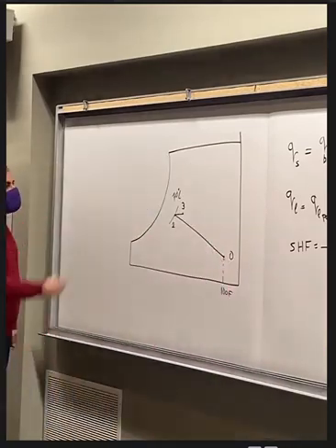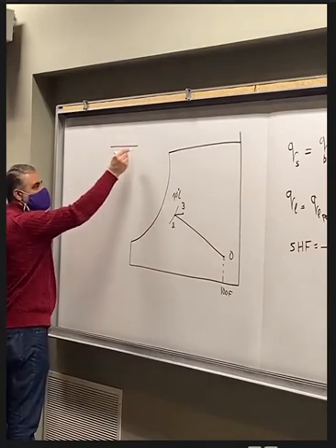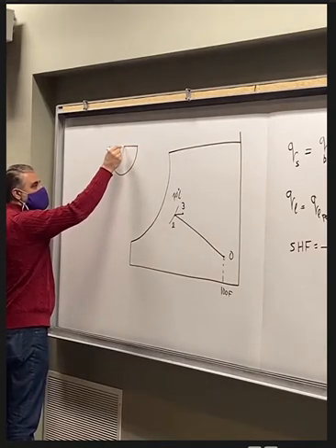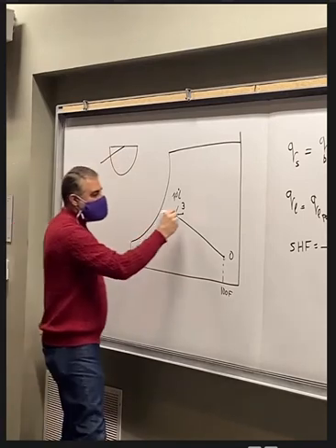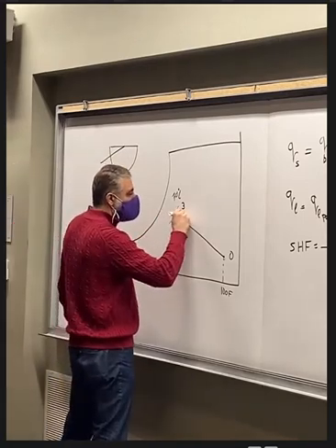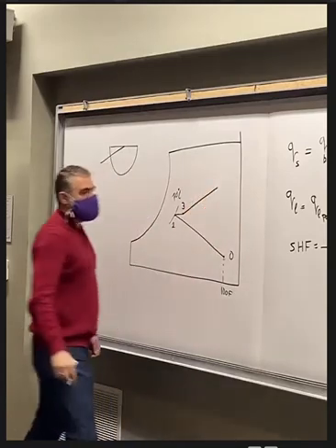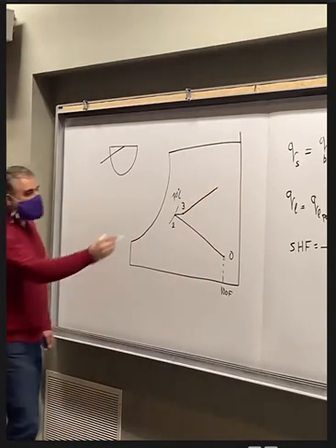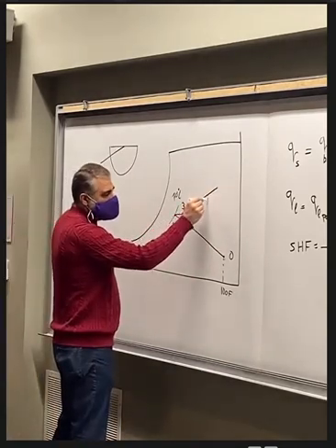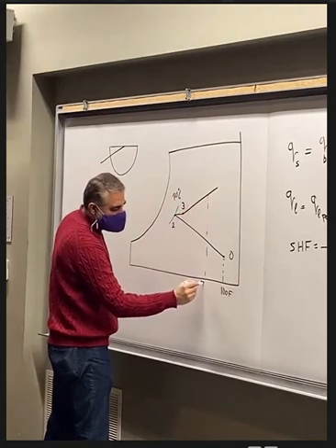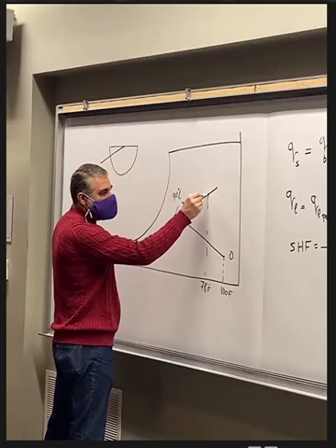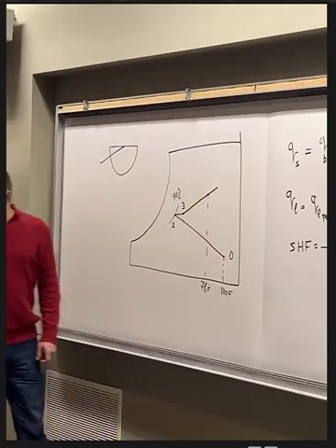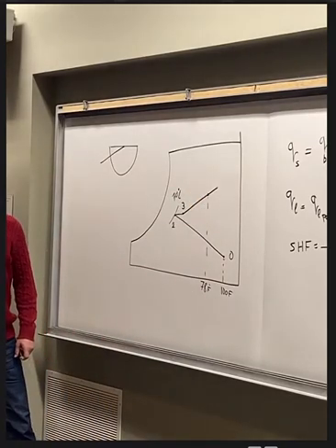And that will be a certain value. So if we go to the psychrometric chart now and we draw SHF, then we can draw a parallel line. That line will intersect with the temperature equal to 78. So that means we can find point number 4.